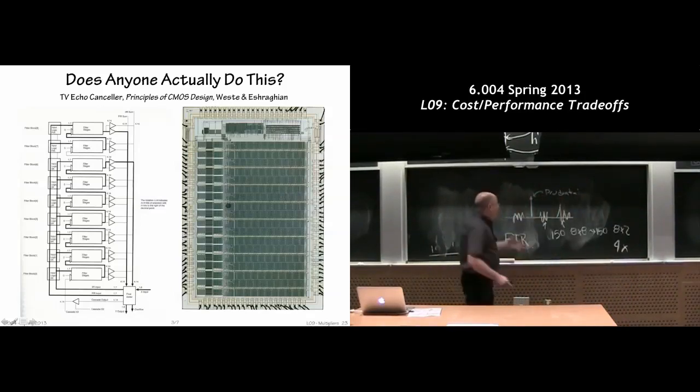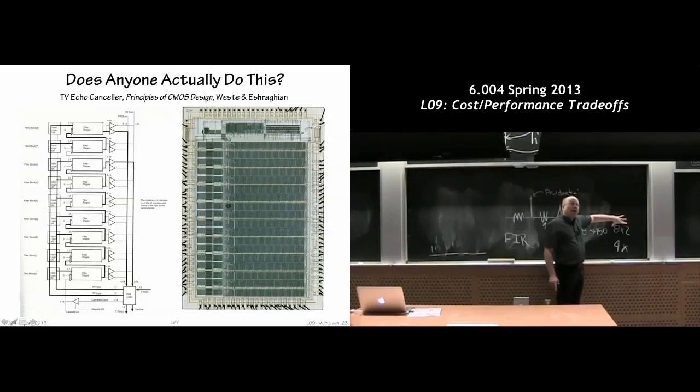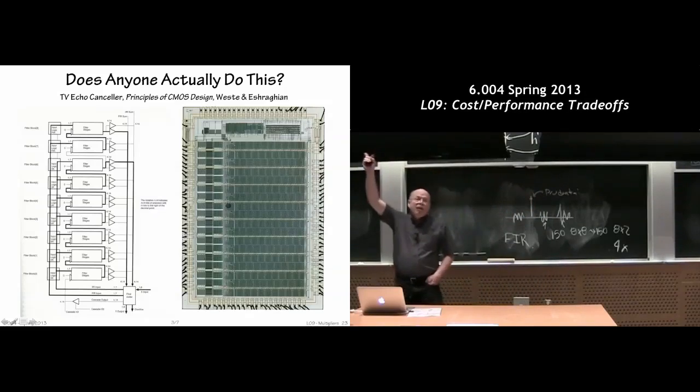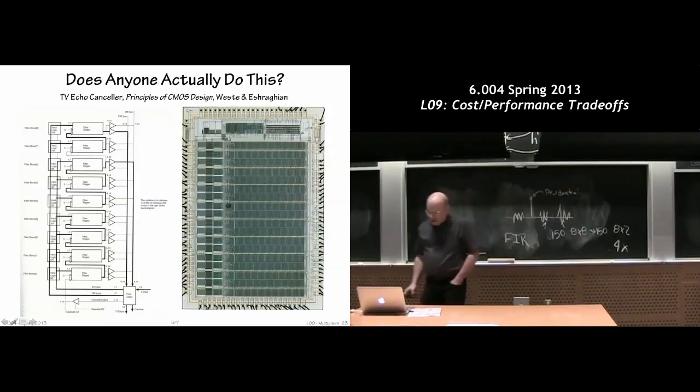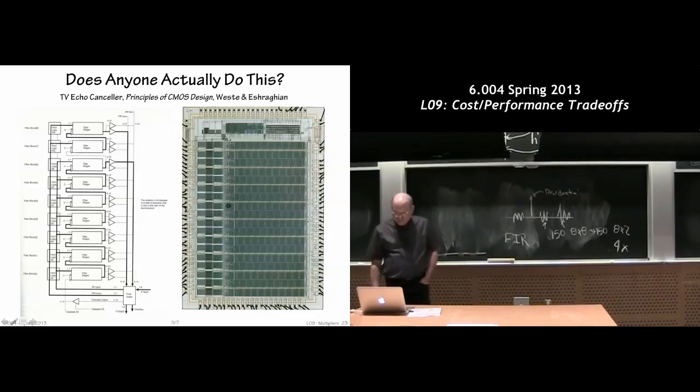In other words, what we did is we took advantage of exactly the transformation I just showed you to build a much smaller multiplier and run it 4 times as fast, and then accumulate the partial products in a register, which allowed us to take a chip. This chip, if it was 4 times bigger, would actually be hugely expensive. And so by doing this sort of trading the ability to run at a faster clock cycle, but use a smaller piece of hardware, made a huge difference in whether this was a chip that was alive and well. And in fact, this is circuitry that you can find in most of your TVs today. So it was a fun project.